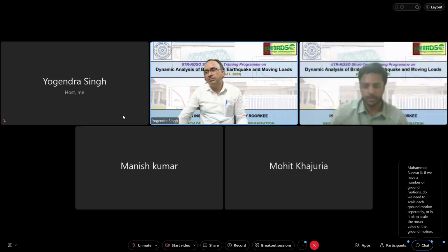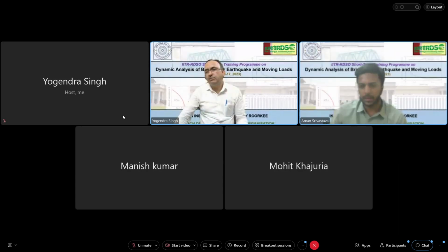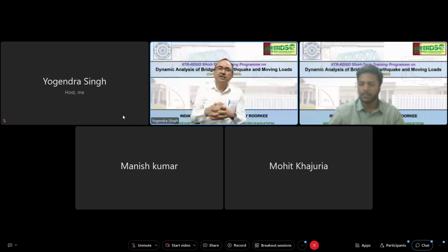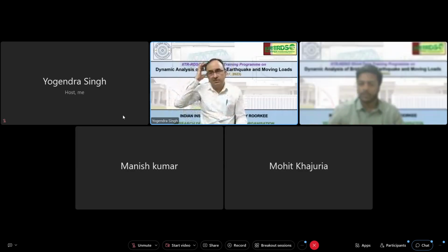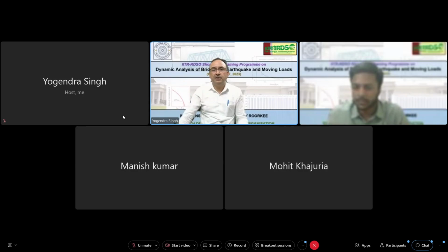Okay, sir. We'll close the session here. One more from Mohammed Nawaz. If we have a suite of ground motions, do we need to scale each ground motion separately, or is it okay to scale the mean value of the ground motions? If you are considering a large number of ground motions, let's say 20 or 30, it is okay to scale the mean and then take the mean value. But if you are considering only 3 ground motions, then this type of scaling will not work because we have to consider the envelope response. And when considering the envelope response, if you scale the mean, the envelope may be too conservative as compared to the mean. So it's better to spectrally match or scale individual ground motions.